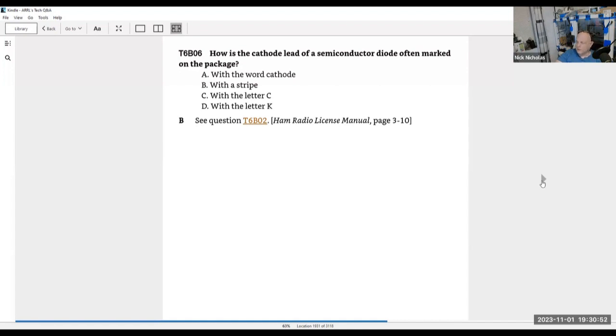There is one exception to this. The Zener diode, which is a voltage regulating diode, always goes in the circuit backwards. It's designed to regulate by taking advantage of its breakover barrier, and it's utilized in reverse so that it can regulate voltage. Current doesn't really flow through it because of this.